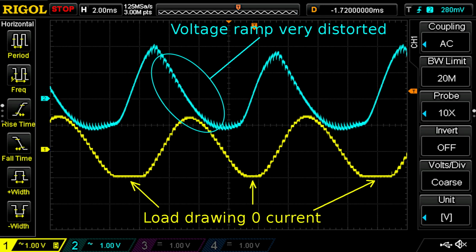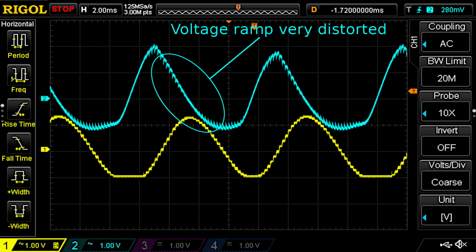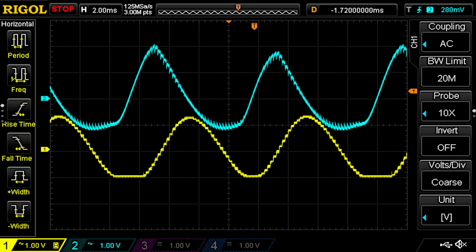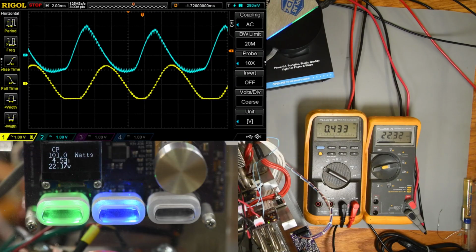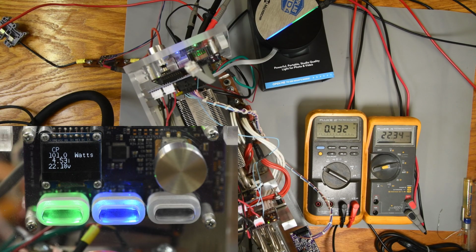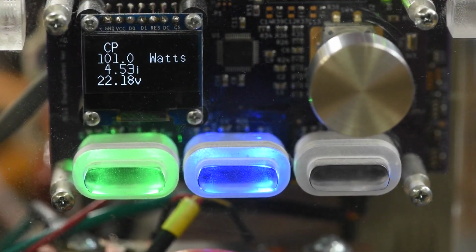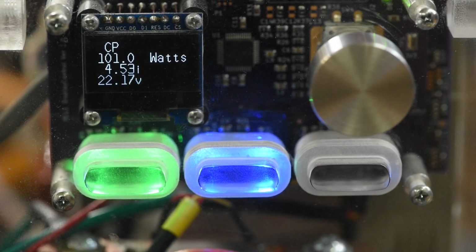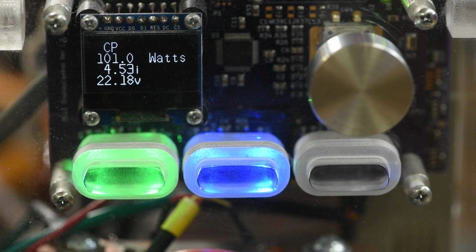And if I were to remove the clamp altogether, I could see the load being turned on full tilt for some time interval, and it would probably end up blowing the fuse in the power supply. I see the constant voltage mode being a problem with a DC supply with really much ripple at all. At least with the current rate clamped pretty low, I don't see it destroying anything.